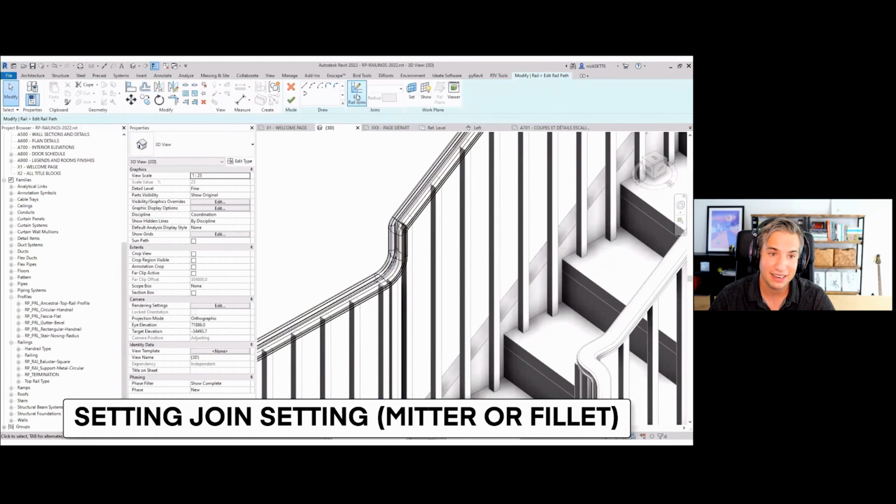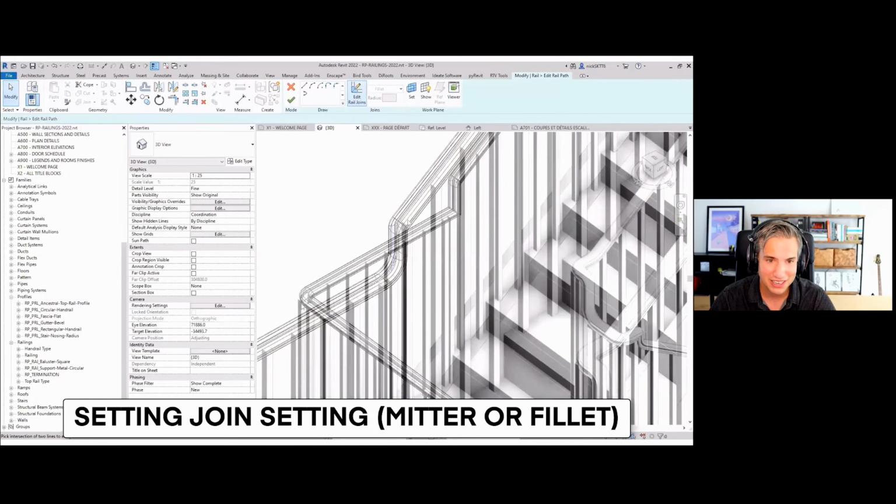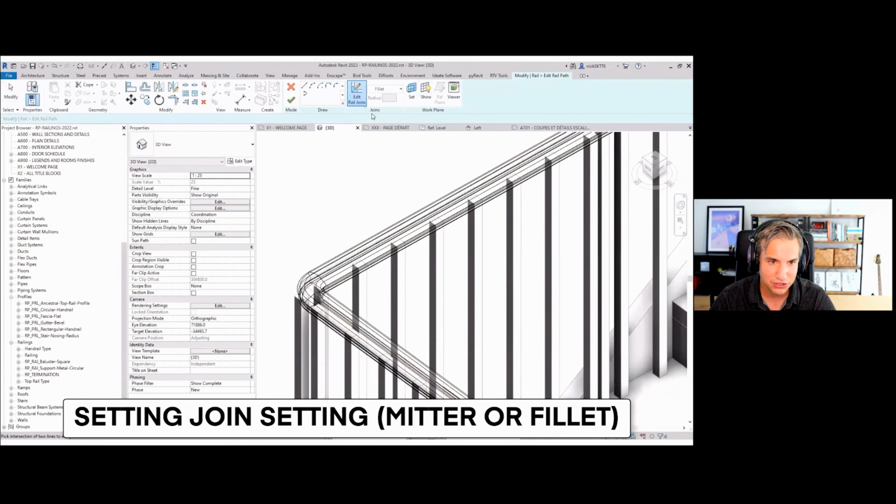And finally, click on edit rail joints. So quite a long way to get there. Then with the snaps, you should be able to select one of the transition, select it, select fillet, and then you can set any radius value you want. So in this case, 200.